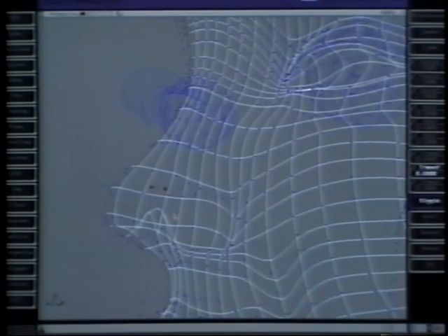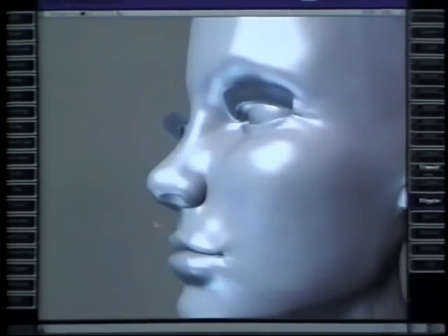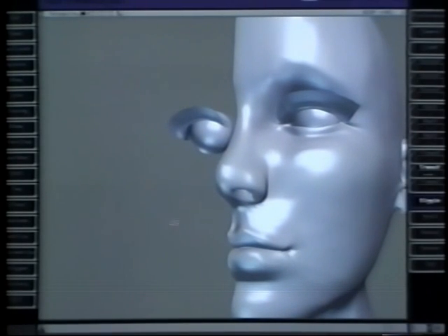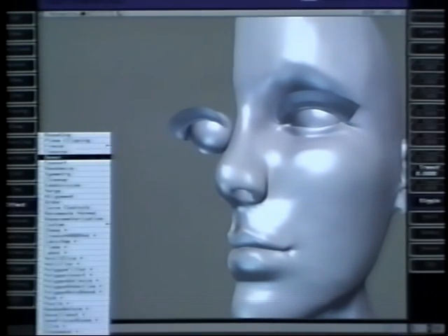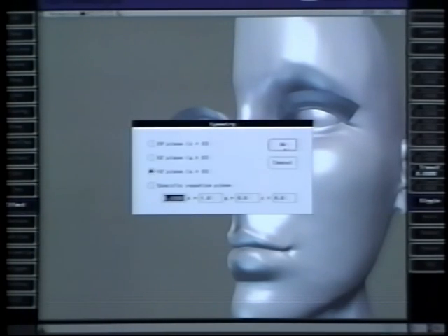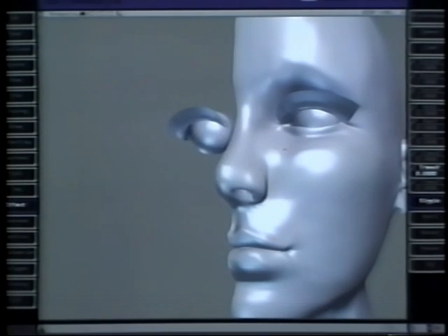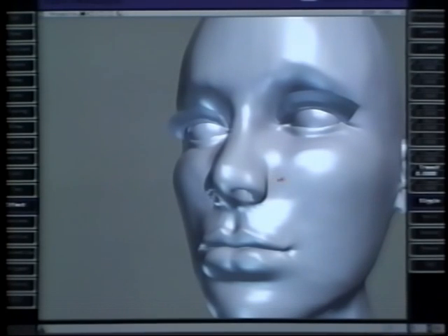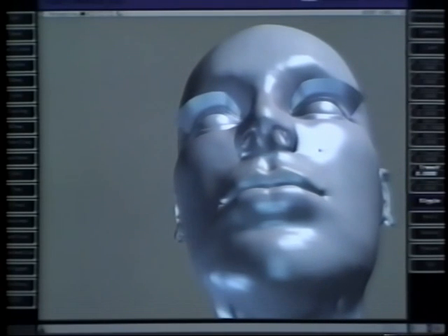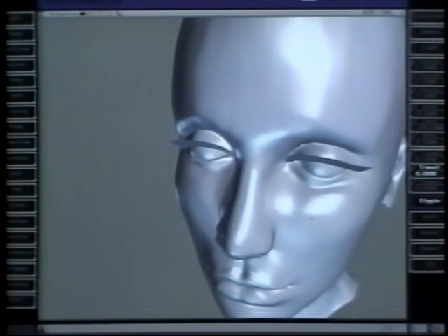To better inspect the work you do near the center of the face, we can select the half head and use effect symmetry to reflect it over the x-axis. Some people find it distracting to deal primarily with half a head at a time, but for detailed models where you could spend an hour dragging points for a single feature, the potential time savings is hard to pass up.